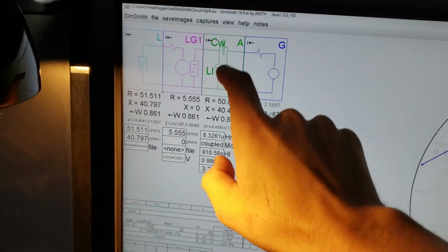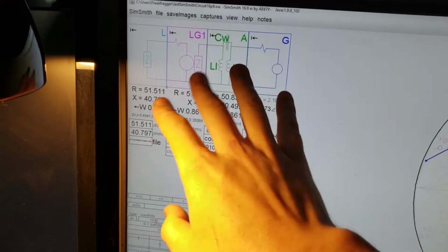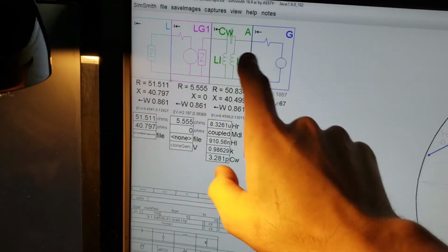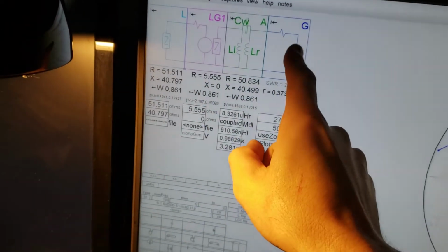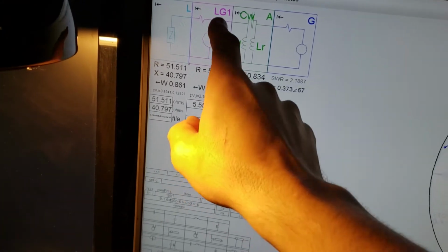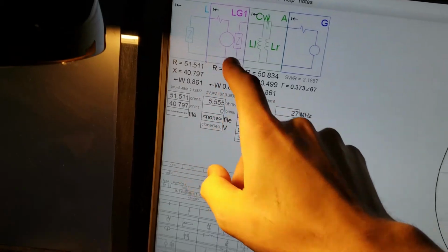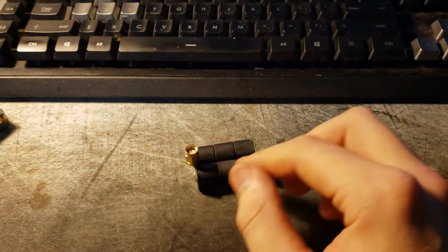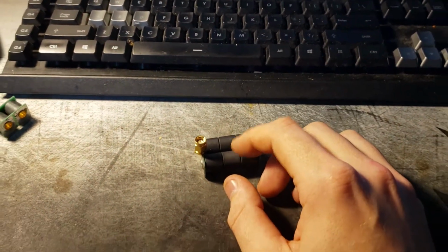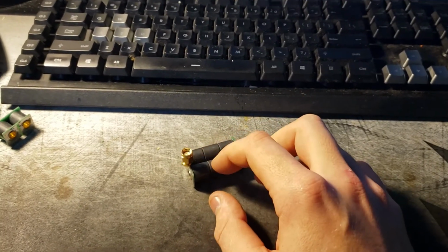So this winding would actually be our output 50 ohm side. So we have to think about this kind of backwards. We've got our generator on the output and our load on the input, but in reality, think about it backwards. So this side would be the antenna, and then this side would be the transistors. So remember that: antenna, transistors. Okay, so this is simulated with 3 turns of wire. So imagine there's 3 turns of wire, which would make this a 9-to-1 transformer. 2 turns is a 4-to-1, 4 turns is a 16-to-1, 1 turn is a 1-to-1.